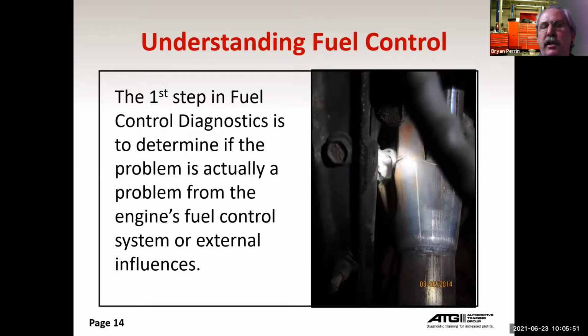You really need to heat it up in an oven to get it up to temperature to get good penetration on the weld because of the mass. You can heat it some with a torch. I have done so, but cast iron flows very differently than steel does and has air pockets in it. So it's a very different characteristic. Normally cast iron is just replaced, and certainly if cast iron breaks in two, it's just replaced. Not that it physically can't be done, it's just normally not done.